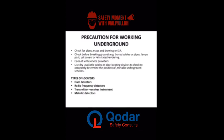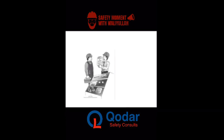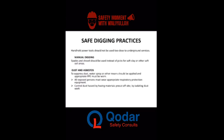Having talked about overhead power lines, what about when walking on our ground surfaces? Well, as safety officers, we want to consult with our management, with our team. We want to check for the plan, the map, or possibly if an EIA has already been conducted on that building. We want to see if there are buried cables, underground facilities, and all that. There are detectors that can be used, which are already stated in this slide, such as hum detectors and metallic detectors. These detectors check for all those things.